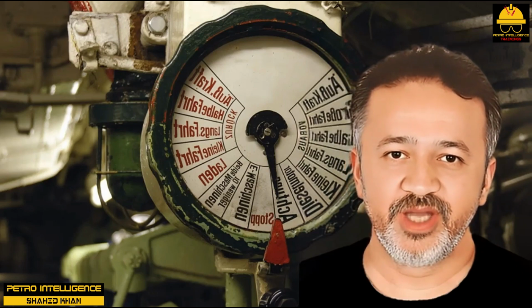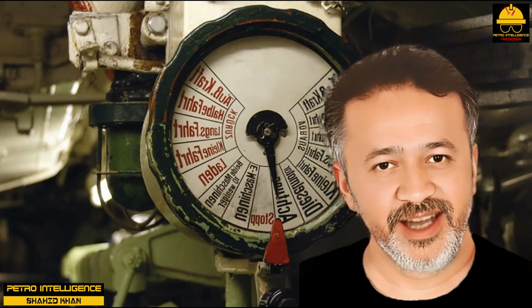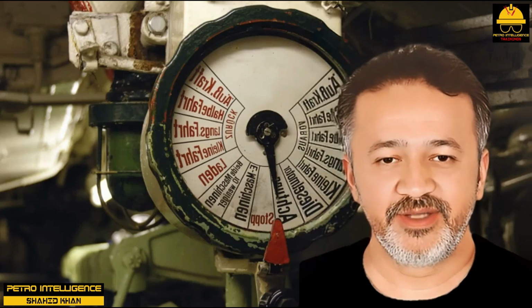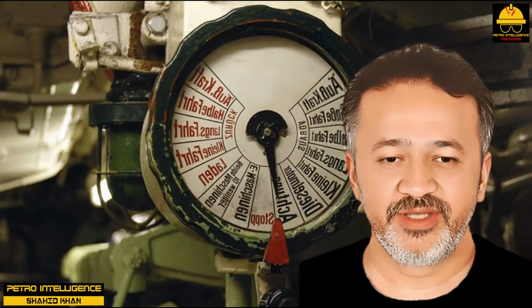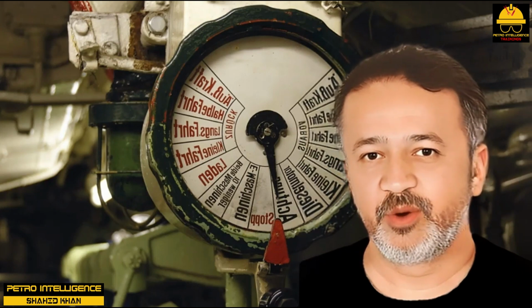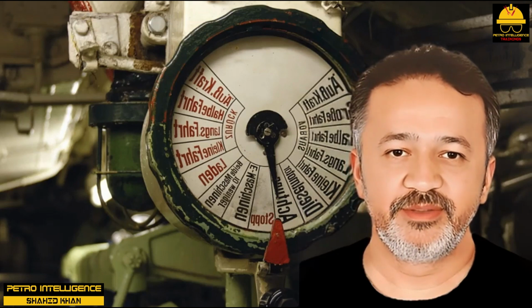There are three commonly used pressure scales in the manufacturing environment: gauge scale, PSIG, absolute scale, PSIA, and vacuum scale, mercury. Process flow measurements frequently are taken by one of the following devices: a flow transmitter, nutating disk meter, oval gear meter, rotameter, turbine flow meter, weir, and flume.